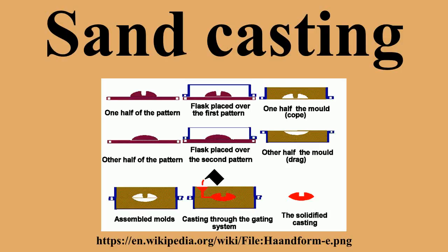The choice of sand has a lot to do with the temperature that the metal is poured. At the temperatures that copper and iron are poured, the clay gets inactivated by the heat in that the montmorillonite is converted to illite, which is a non-expanding clay.